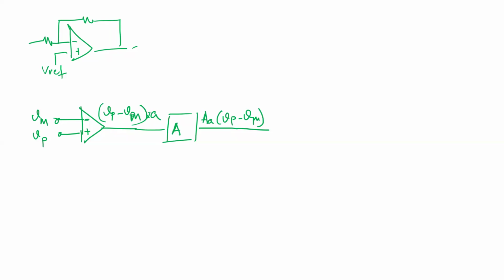All right. So if I don't provide the output stage with that current, then this output will just collapse. Okay. So if this was 100 ohms, then I need like 1 volt swing and I need 10 milliamps, right? And that 10 milliamp has to come from this guy. Okay. So typically when you're doing generic op amps, you need a specific output stage. Okay. So typically it's called a class A, B output stage.